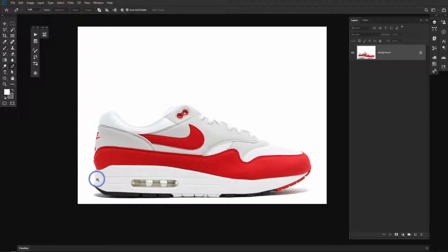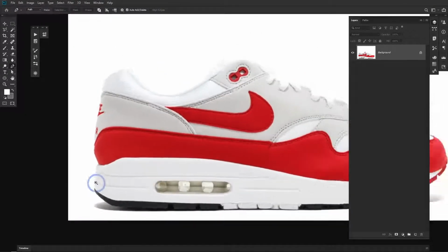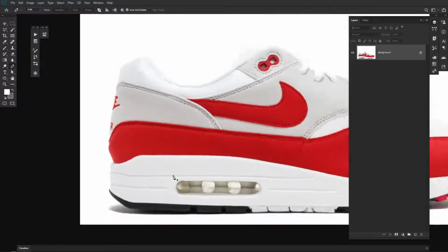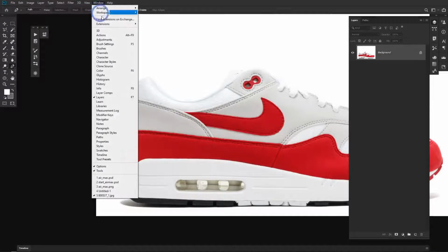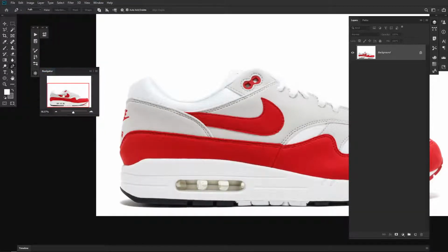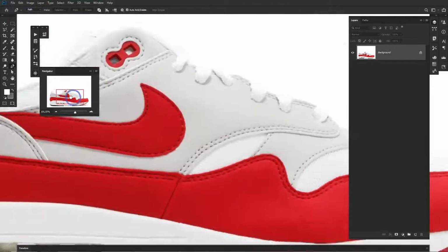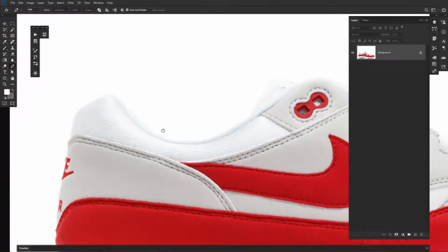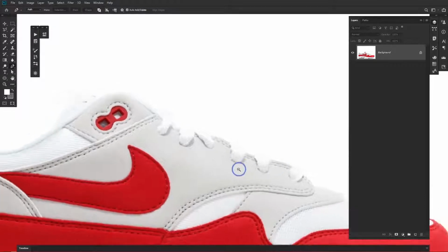You can also use the zoom tool: press Control and the space bar in order to zoom in, or if you're on a Mac, hold Alt or Option and just use your mouse wheel to zoom in and zoom out. There's another way to do that. You can use the Navigator side panel, under the Window menu, to zoom in or out and move around these different elements. It's because we're going to need the space bar to get the little hand to move around the different elements that I need to cut.